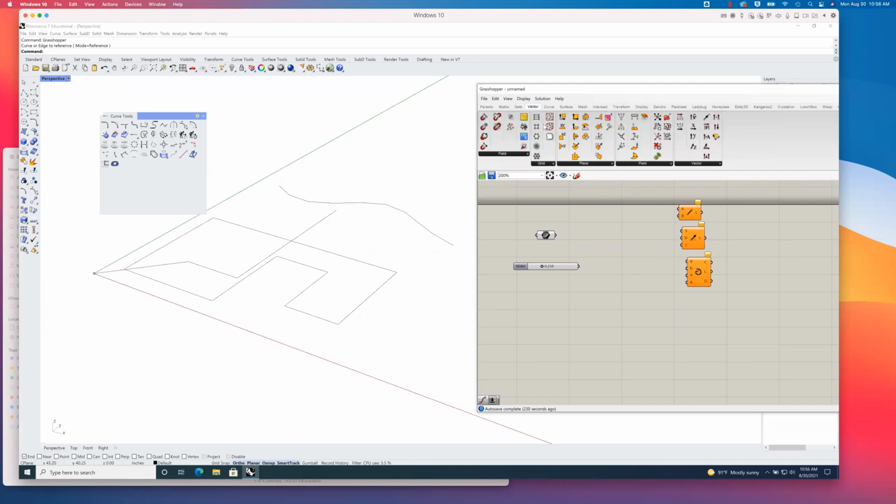A couple of other tools I use for some of those wall drawings. If I go to the vectors tab and I go to grid, there are a number of different ways to populate an area with points, and a structured, ordered grid is one of the easiest ways to do it. So there's a square grid, triangular grid, rectangular grid, radial grid, hexagonal grid, etc. I can populate a two-dimensional area, in this case with 100 points, with a seed engine of 1. The region by default was set to width of 20, height of 10. Maybe I'll just do 20 and 20 each.